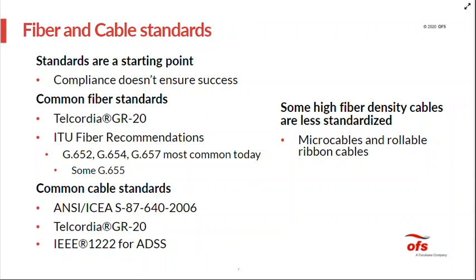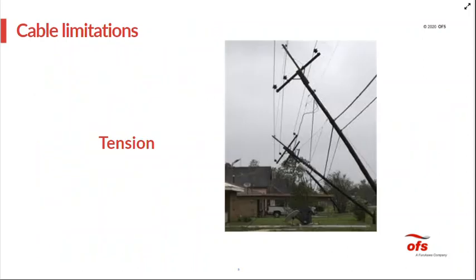Just one other note is that some very high fiber density cables are less standardized. So certainly over the last decade, we've seen many different generations of micro cables, and also the advent of rollable ribbon cables. And these are a little bit less standardized in comparison to some of the other products. And so you want to make sure, again, that you understand the products that you're working with, and that you are applying the appropriate installation recommendations and do's and don'ts to the proper cable.